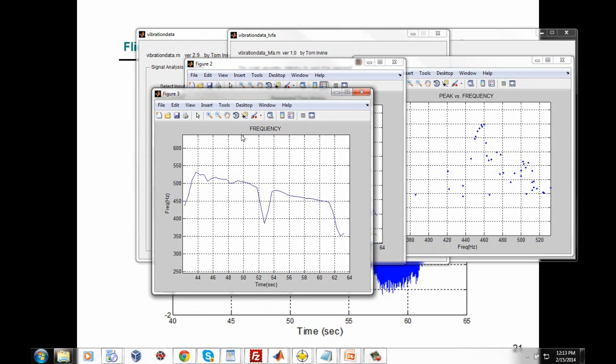Now here's what the dominant frequency is doing. Within each half-second segment, we can use a method like counting the zero crossings, for example, to determine the dominant frequency as a function of time. And we're going to ignore parts of this curve. We're going to ignore this startup here where there was a quiet period, and this ending here where it also went back to a quiet period.